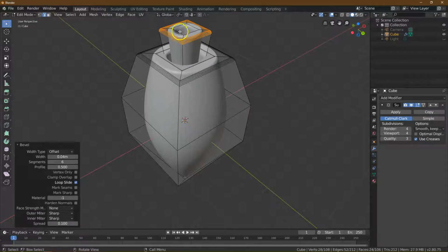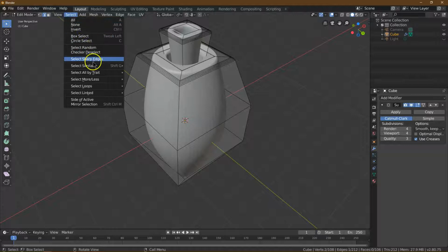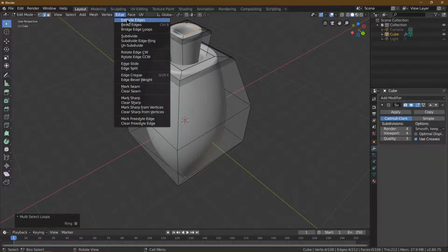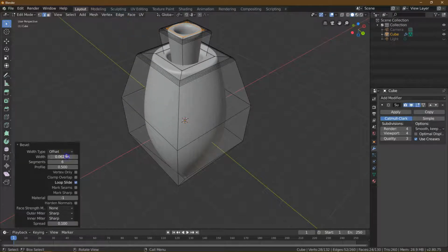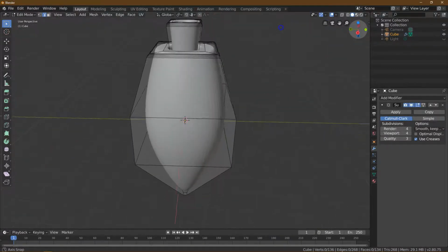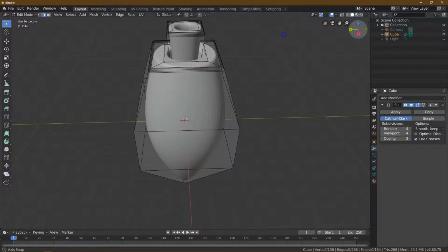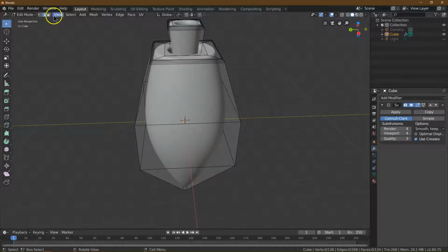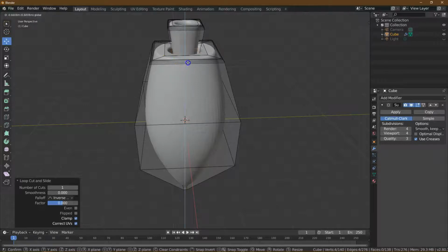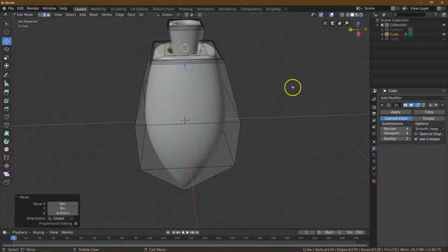is looking good. So let me click on this line, select, loop, edge loops, edge, bevel edges, looks good to me. Okay, so we have that first stage of the rocket. We're actually going to do another mini one now, and so I'm going to use a loop cut and click right here, and then right away I'm going to click on move because I want to move this up, right about there.